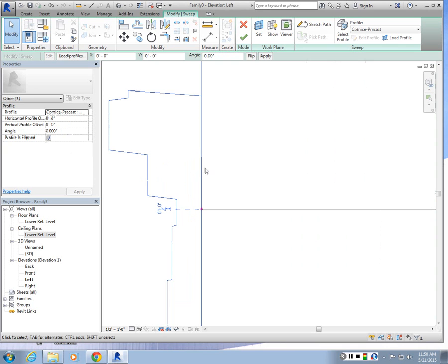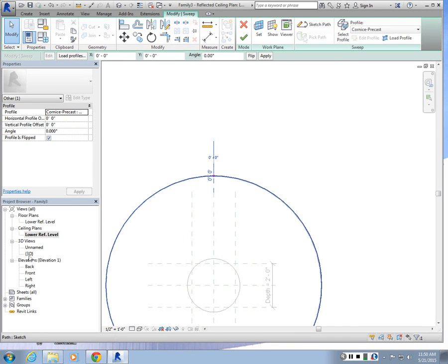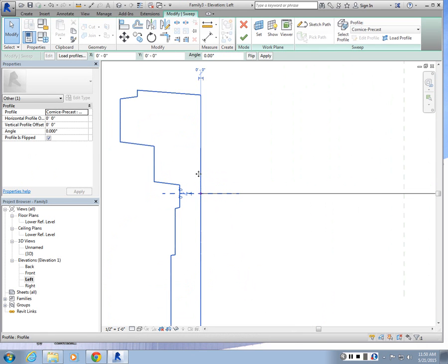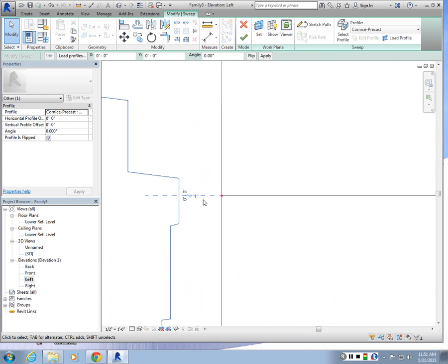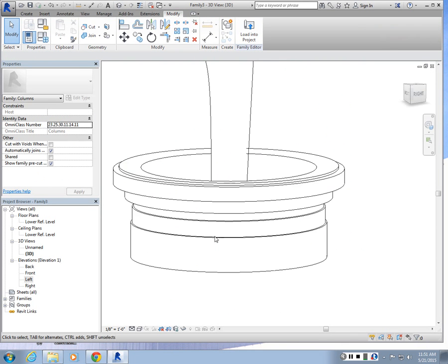Now, this axis is basically located on the path that we created for our sweep, and then it gives me a coordinate system on that sweep path line, where I can draw a profile and then sweep it along that path. And I'm actually seeing it here, these two lines, and the red dot is basically the path where this profile is on. And I'm going to check for now to show you what it does. So it just created this sweep.